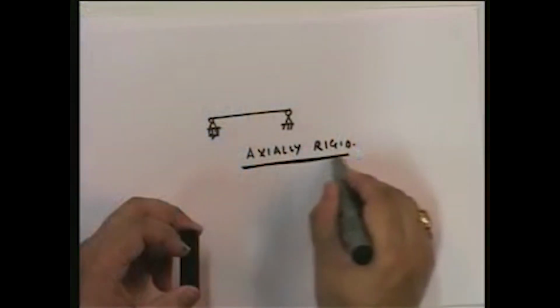Now note, in general, think about it, when you find out for a statically determinate beam, what are the forces that you normally find out? The shear force, bending moment. Do you ever find out the axial force? You don't. So therefore, implicitly without knowing, you are actually neglecting axial deformation. You never explicitly mention that. When you're analyzing a frame or a beam, you never explicitly state that. But you're implicitly assuming that the axial deformations are neglected. In other words, the member is actually rigid.